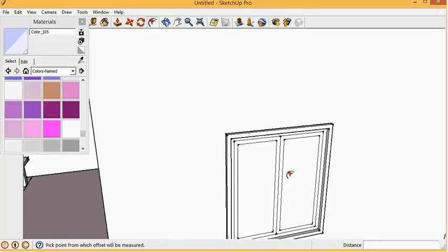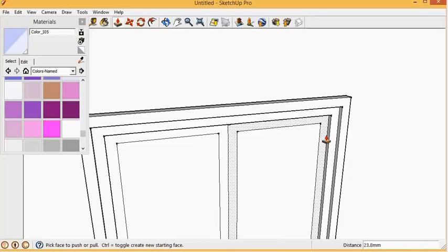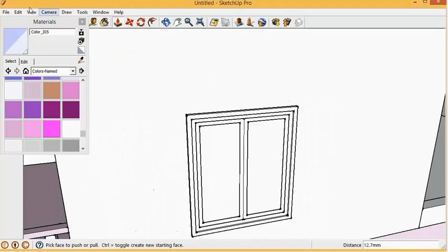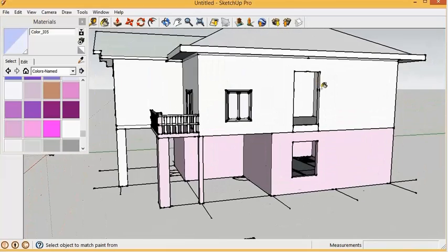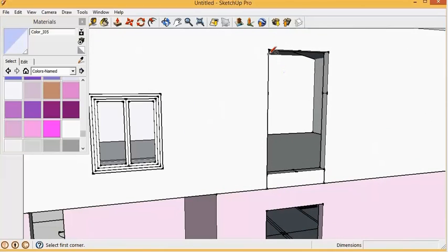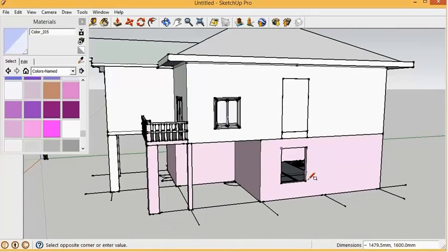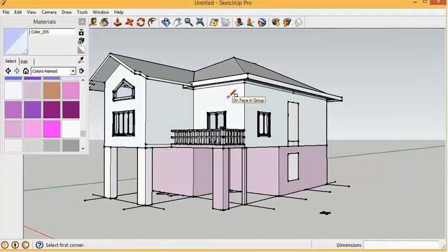Well, probably the easiest way to do that is just to draw your way into it. So I'm just going to use my line tool. I'm going to select my line tool, draw along the red axis until I get a snap to the blue, and then draw again until I snap onto my guideline. So now I have the point with which this will intersect. So again, one more line, and I'm drawing over to this top ridge of the roof.